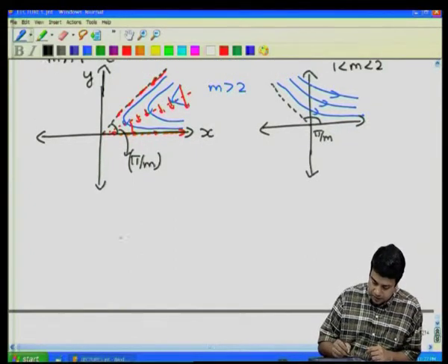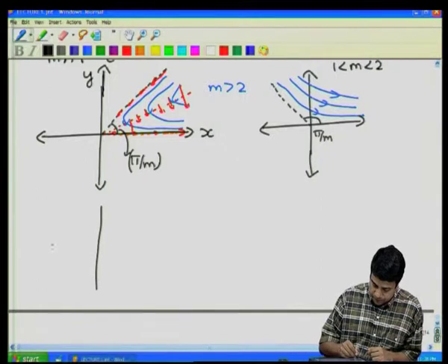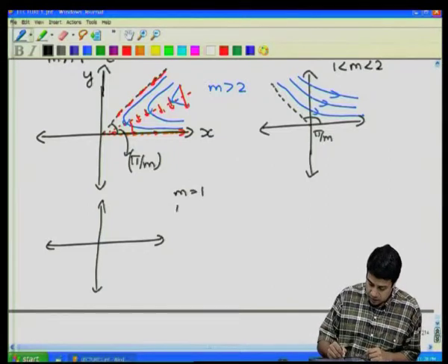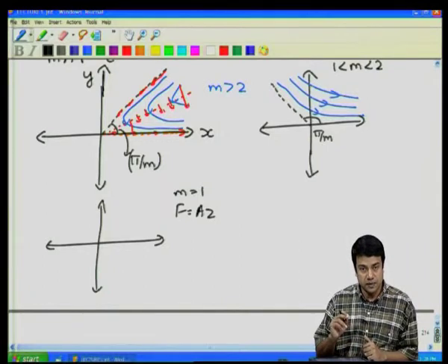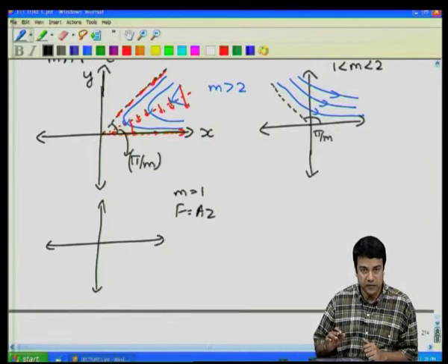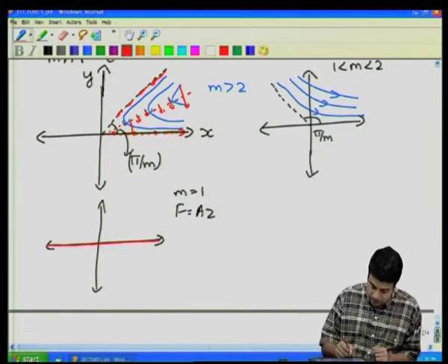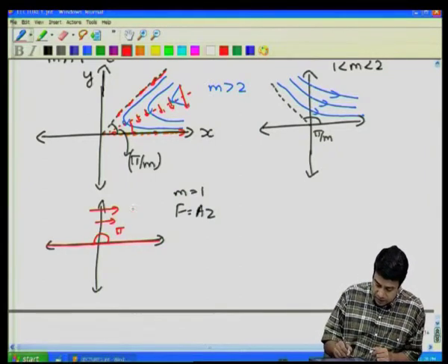For m exactly equal to 1, f is equal to a times z to the first power. That is what we had solved first. When f is equal to a times z, w is equal to a. So, the velocity is a constant. So, that represents a flow in a corner. It is not a corner really, but just a straight flat surface. This subtended angle is just pi. The velocity field looks something like this.